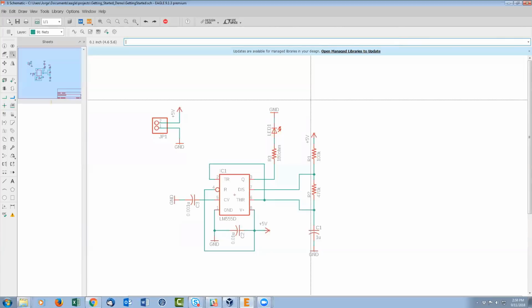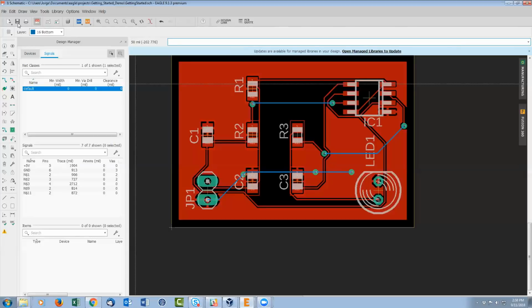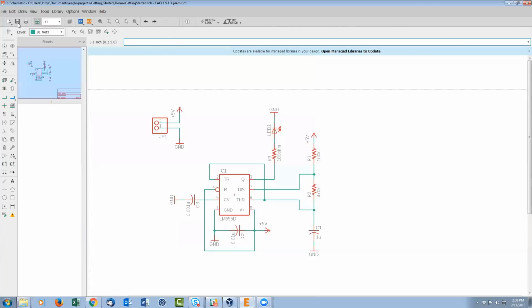Robert is asking, can you just teach him really quick and review how you toggle between board and schematic, please? Sure. So basically toggling between board and schematic is up here. It's this toolbar. The fourth icon from the left in both is to switch. So if I left click now, schematic. I'm right back over it. Left click now, board.